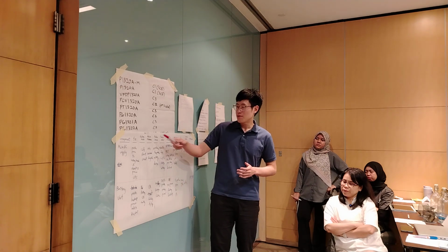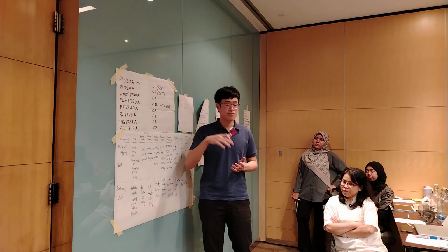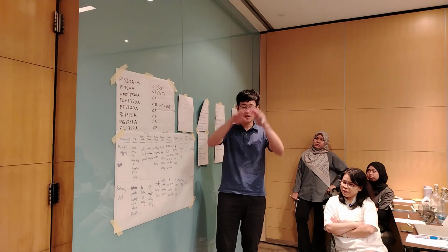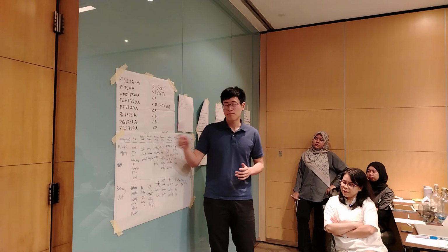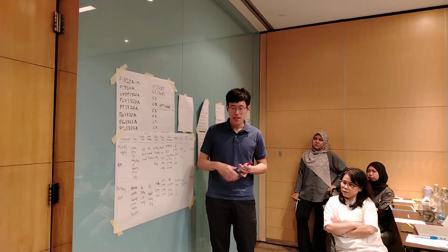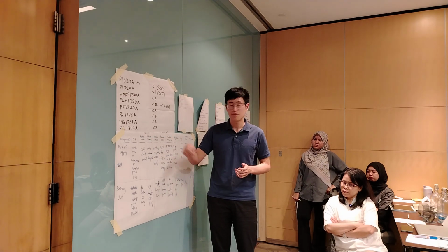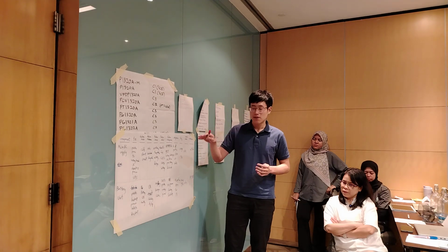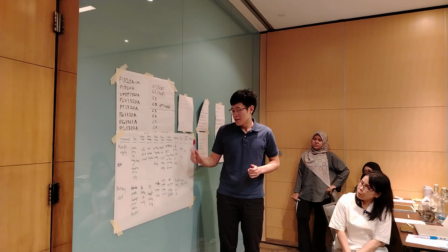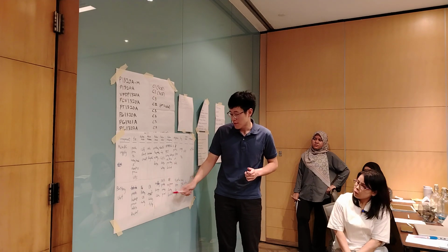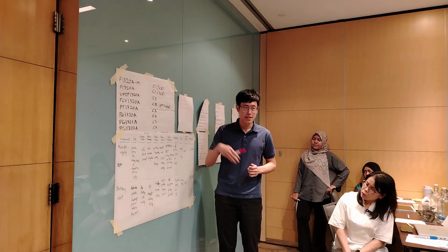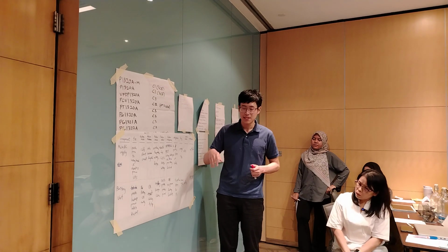For example, if the UPS is for the NMC, if you ever go to the panel room, you will see a lot of panels. Basically all the power of the panels is supplied by the UPS, so that during a total blackout, we can still see everything on the panel and monitor all the processes. So the consequence of the battery circuit breaker failing is probably no power supplying to the NMC, so we cannot control all the processes.